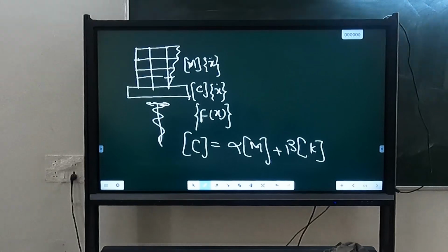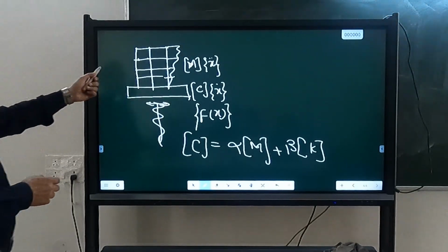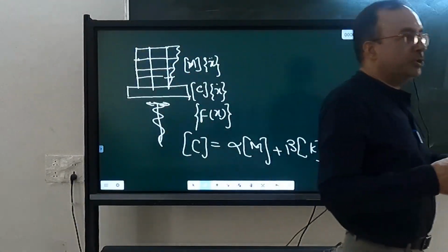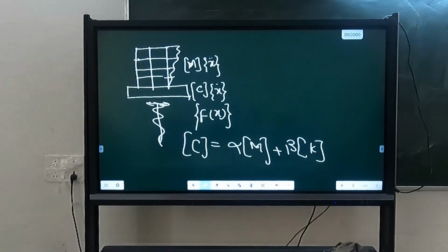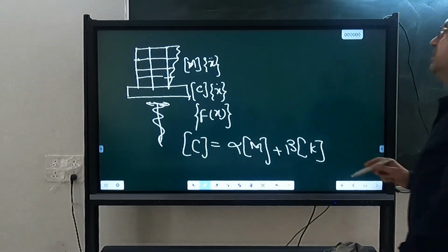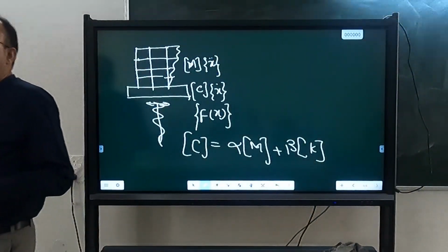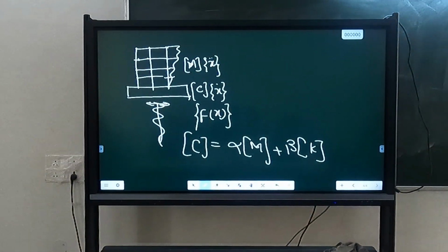And we are simulating not only the displacement, we are simulating the non-linear behavior. So plastic rotation, how it is happening, energy dissipation, cyclic degradation. Those things are impossible to simulate on a scaled model. So that's the big disadvantage, and that's why with these small shake tables you will find very few studies. Shake tables are not being utilized.